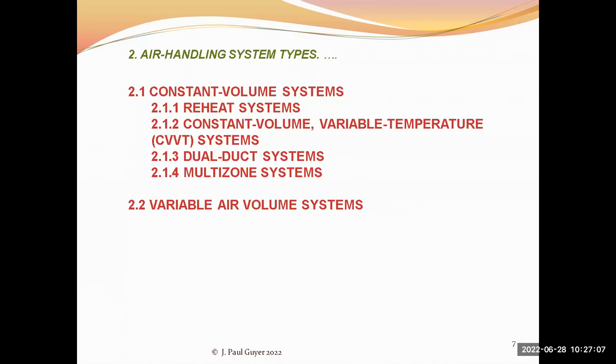And this is energy inefficient because you're using energy to cool it down, and then you're using energy to heat it back up. But that is an approach that is used in some older buildings: a constant volume system with terminal reheat.